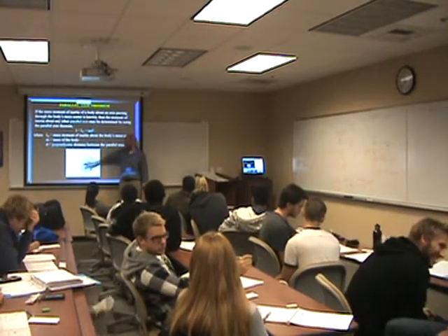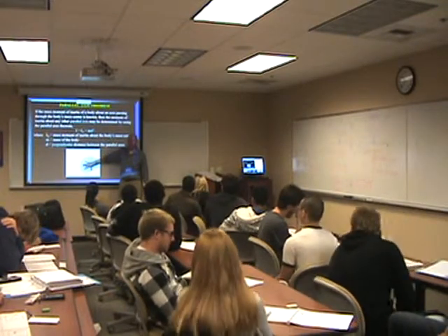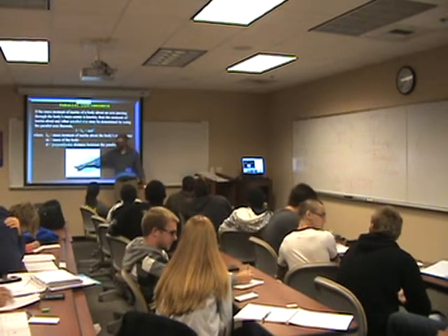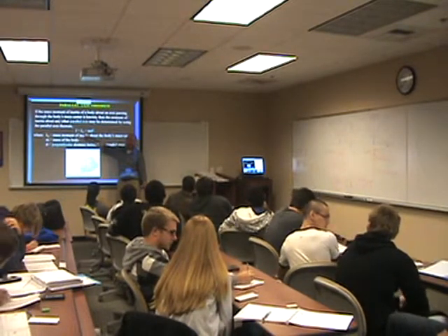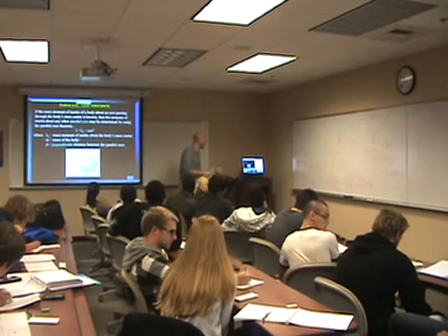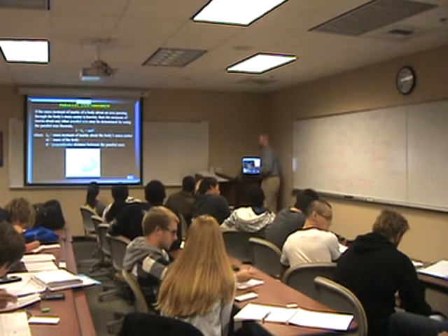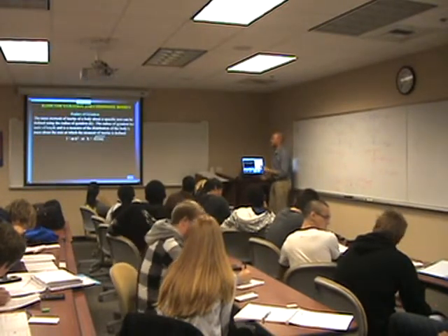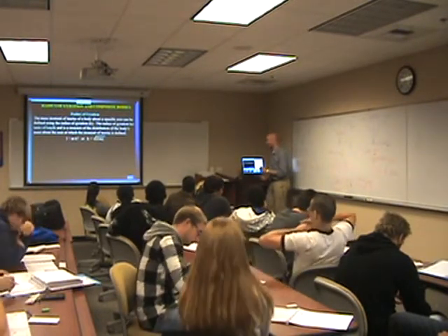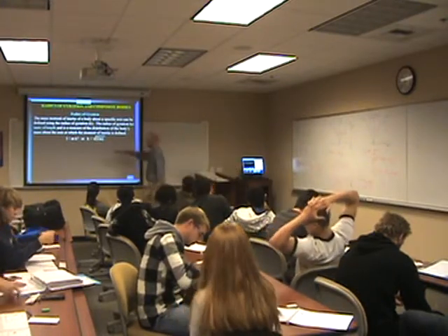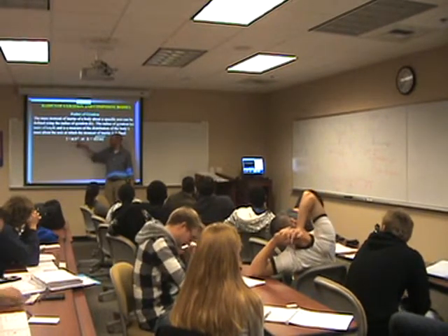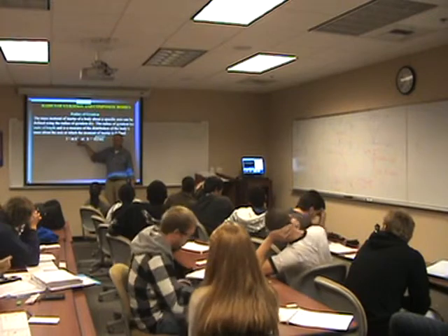And so if someone has already done the calculus for this, if this is a disk or a sphere or a rectangle or a cube or a thin rod, if we're rotating about this, we can let someone else do the hard calculus for us and just use the parallel axis theorem. It's the perpendicular distance between the parallel axes, the distance from the center of gravity. So radius of gyration is sort of a corollary. For an object, we can have I, which is the mass of the object times k, your radius of gyration, squared.